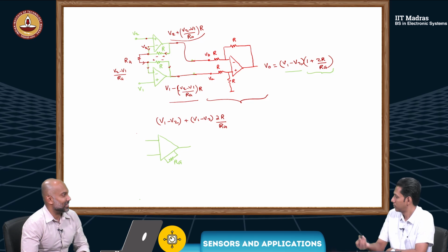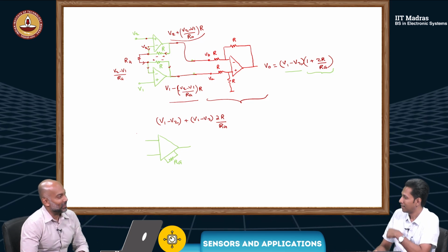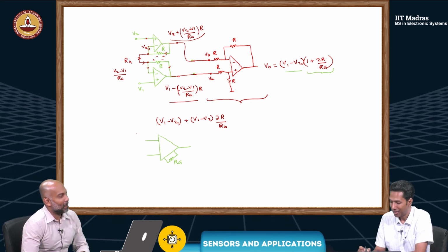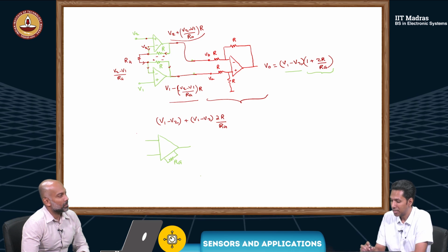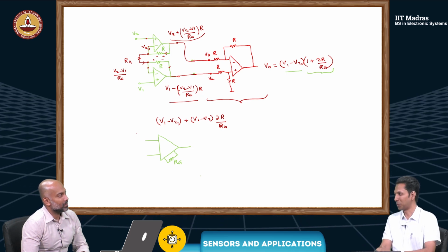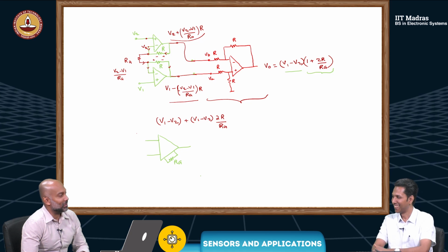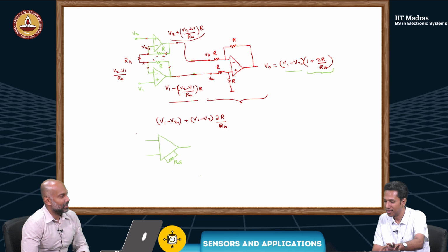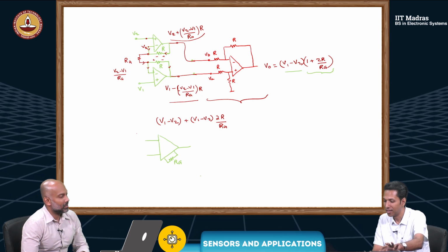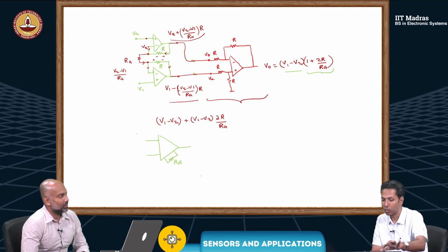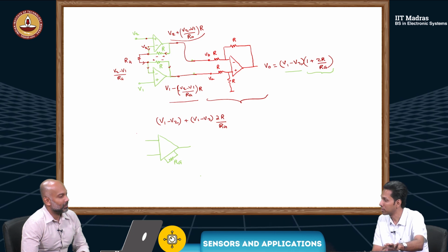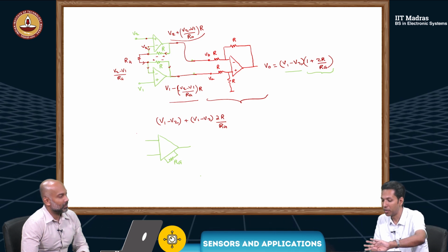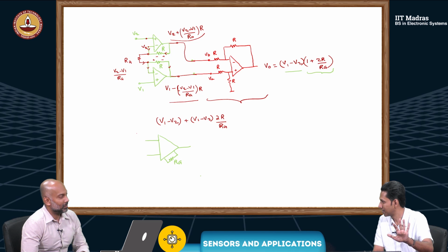The standard ICs, right? Yes. So this amplifier has got a nice name, you know it. Once you have this full configuration, it's getting the difference output, providing very high input impedance, and it has very good common mode rejection, right?